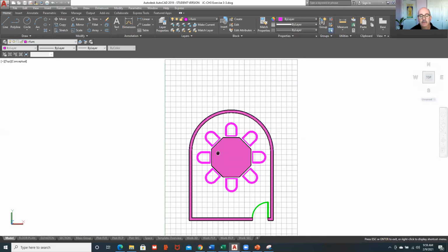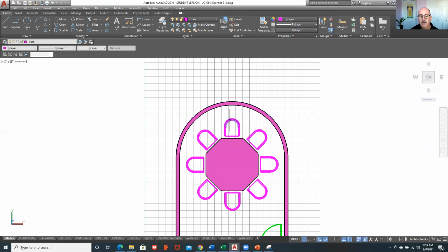So if I wanted to copy this chair over to another element, so if I have a rectangle out here and I want to copy the chair to the midpoint of it, I would say copy. I would select the chair. Notice blue or green. Blue selects everything inside of the box, nothing that doesn't go all the way in the box.